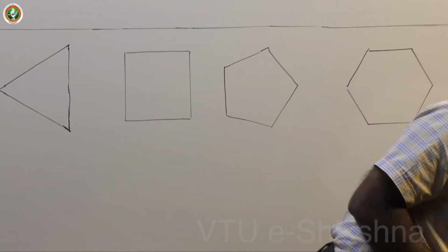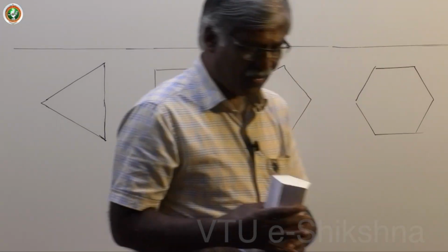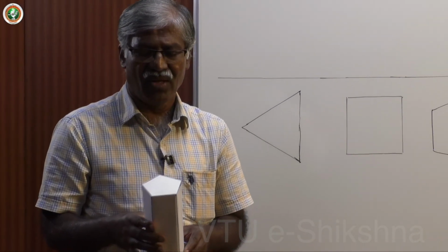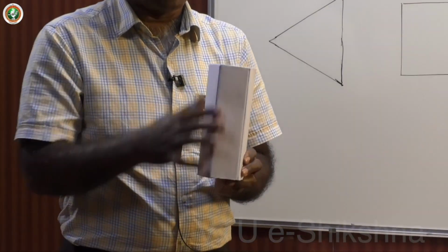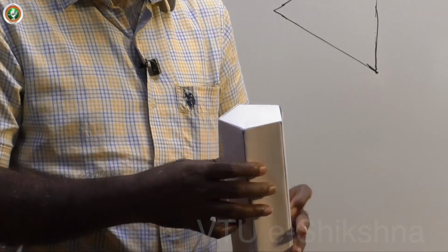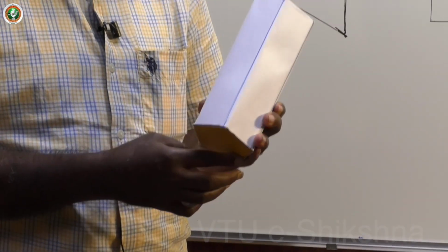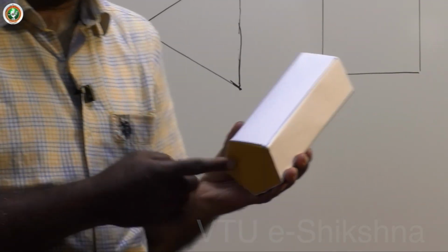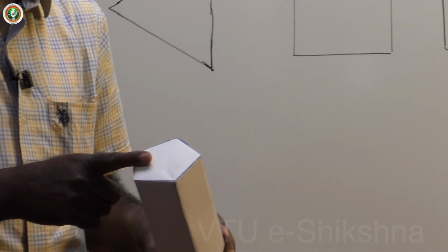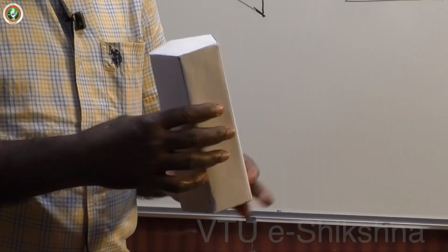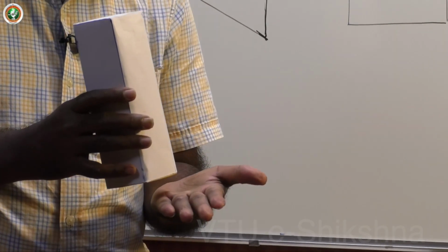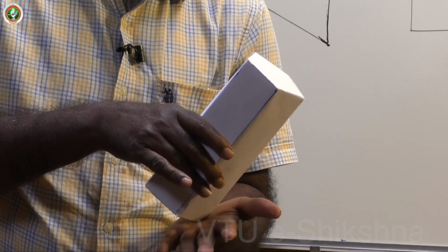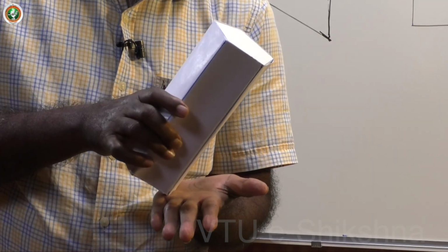Now we have pentagon, triangle, etc., with an odd number of sides. This is a pentagon. We have longer sides, top face sides and base sides. As I told you earlier, for explanation purposes I have kept this dark and this light. Now the reference is: if the question says it rests with one of its base corners, or if it rests with its base edge, like this.